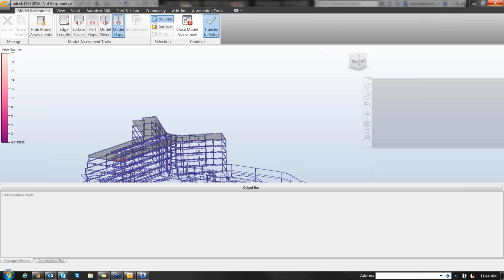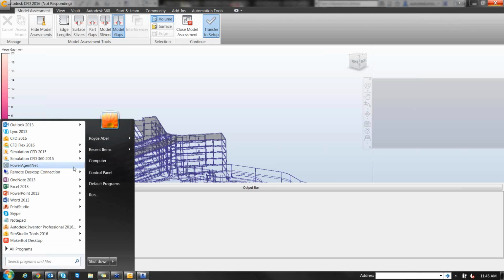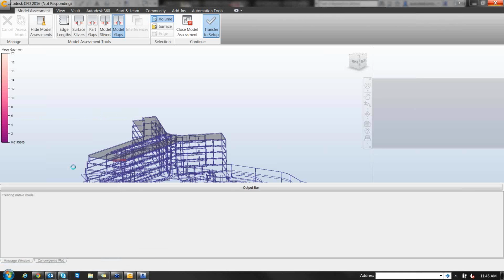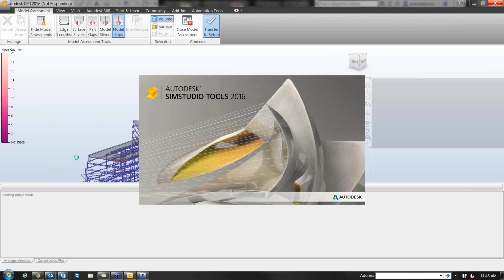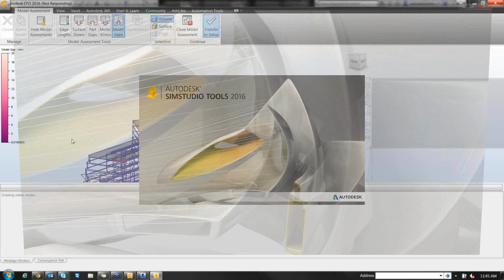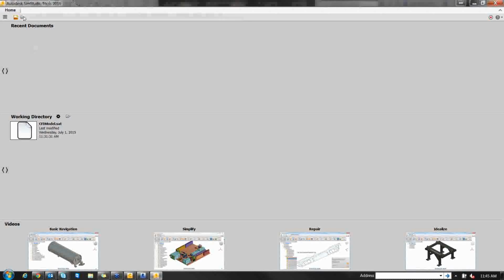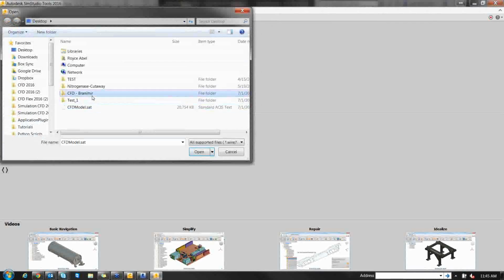Okay, so Richard brought up, can we bring in an STL file? I guess SimStudio can read an STL file, right? To a certain size, yeah, there's a certain polygon limit. Well, actually, you can read them, I think, unlimited size, but the one thing to realize is that STL files are not a format that is explicitly supported in 2015. It's a faceted model. There's no solid geometry. So the only thing that can really support an STL file is if you use the surface wrapping capability.